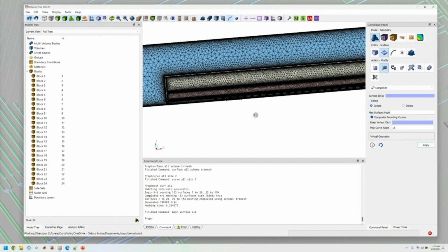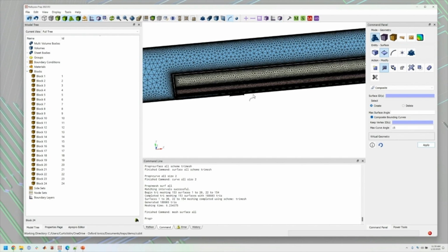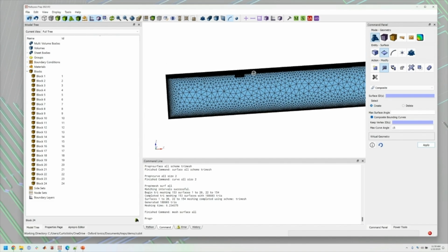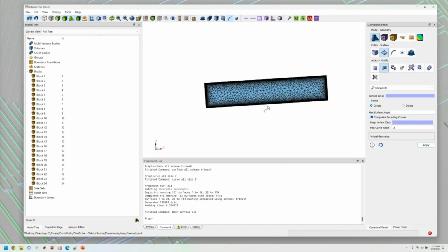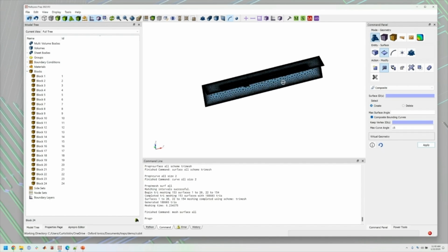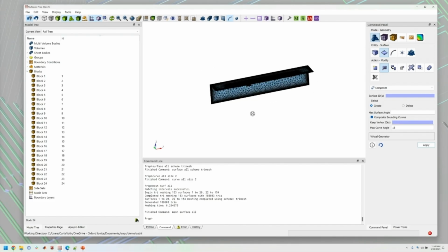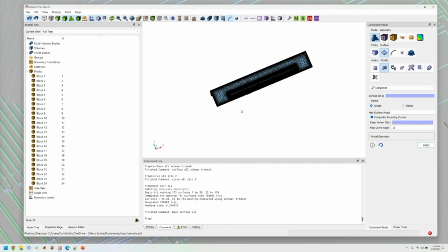This trap does not have that symmetry. The load slot is off to one side, so we can't use that. And then there's a remaining ground plane, which we can have in the z direction, which you could allocate to either placing a ground plane at the location of whatever the circuit board or interposer is down below this die, or by placing a ground plane above it, simulating sort of mesh that's often used in experimental groups to form a Faraday cage above this trap. You can choose which one is more valuable from a simulation point of view.